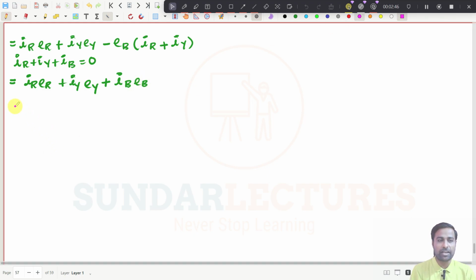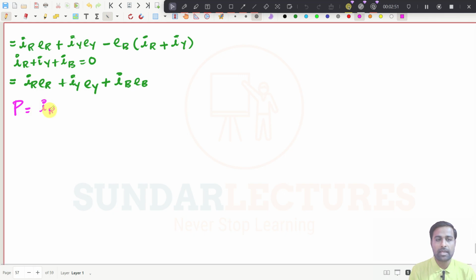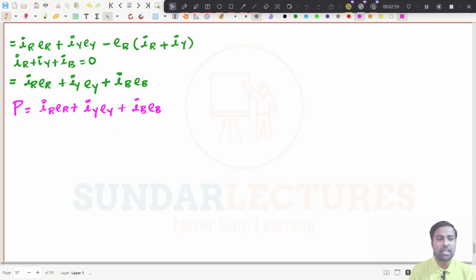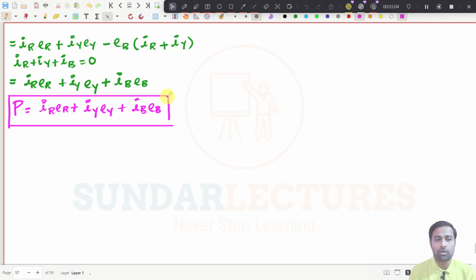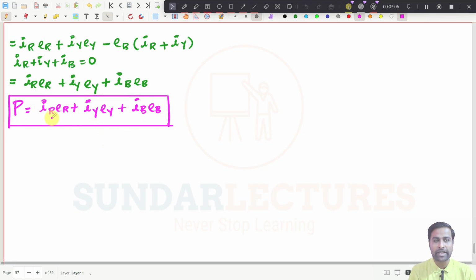Try to understand. The power will be equal to IR ER plus IY EY plus IB EB. See this one now. This is the total power measured. Try to understand this power: this is R phase power, this is Y phase power, this is B phase power. All are added now. So the total power will be what? All three phase power.